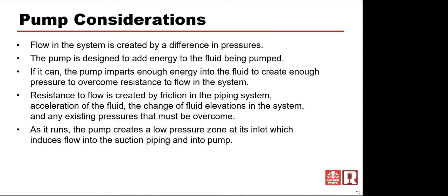If you can imagine a pump that's capable of going, say, to 40 PSI, pumping into a header that's already at 50 PSI, which is being pressurized by other pumps, you're not going to get any positive flow. In fact, you're going to get negative flow. You're going to get flow back through that pump to the source unless there's a check valve to stop that reverse flow. That pump that's capable of doing 40 PSI is not going to be able to push into a 50 PSI pressurized line. Makes sense.